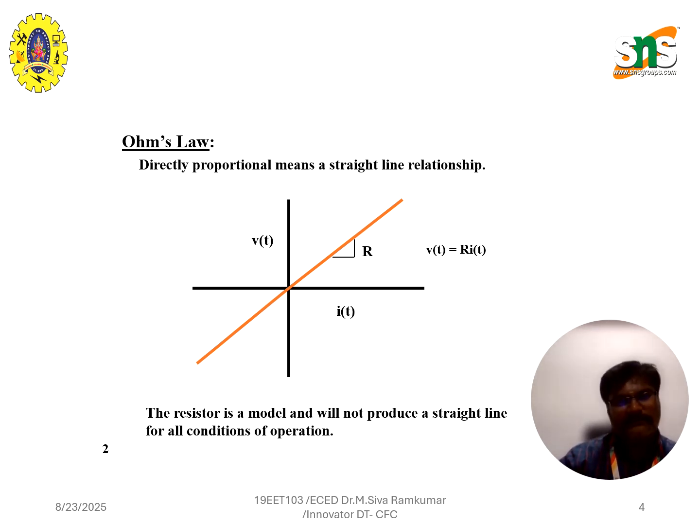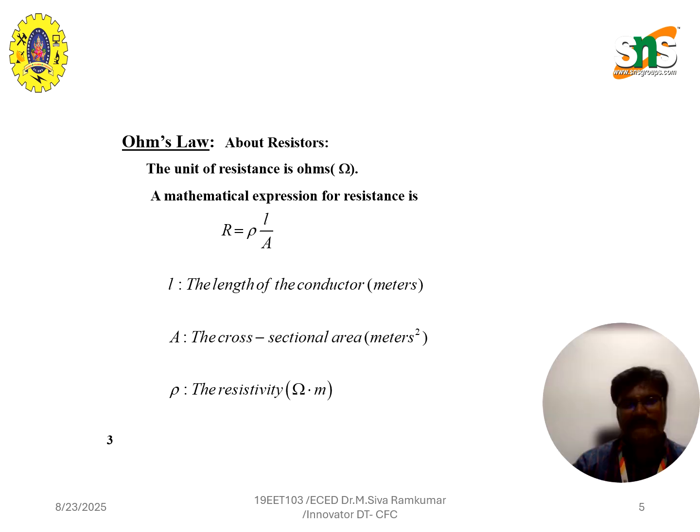When we say directly proportional, it implies that if we double the applied voltage across a resistor, the current will also double, assuming that the resistance is constant. Graphically, this is represented as a straight line when plotting voltage against current. However, it is important to note that real resistors deviate from the ideal behavior under extreme operating conditions such as high current density or elevated temperature. The linearity is lost, leading to non-ohmic behavior, I mean, non-linear characteristics, right?